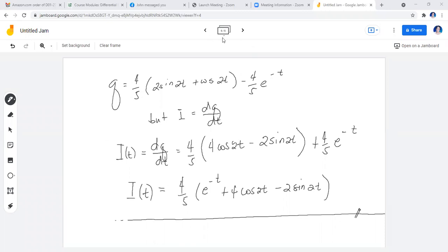Okay, if there's none, okay, there's one here. To clarify, Miss, if there is no presence of voltage source in the circuit, we only have transient current. To clarify as well, your current for an RL circuit, you may be referring to the RL circuit, if it's a complete circuit, will have two terms, the transient current and the steady state current. Now, if your question is if there is no presence of a voltage source, automatically the current that you will be computing is the transient current.